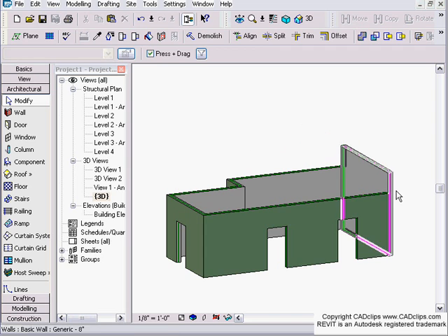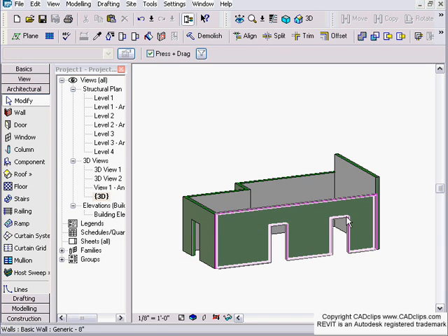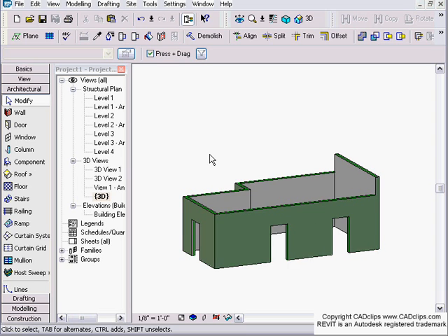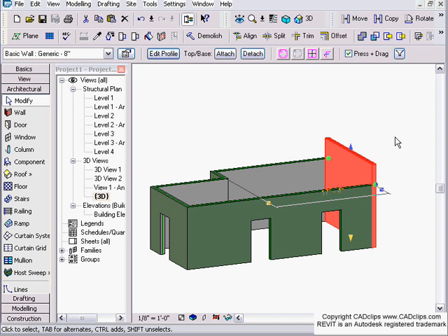And just as a demonstration, when I had said to attach walls, when you create a roof or a floor above any walls and it asks you the question, do you want to attach the walls below? If you say yes, what it does is it automatically projects those walls up to that floor or roof. In this case, I was just playing with different actual heights of this.